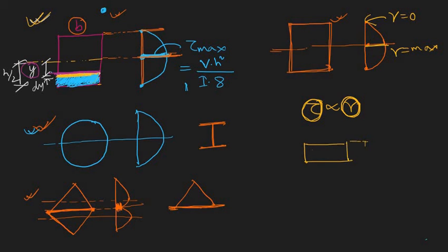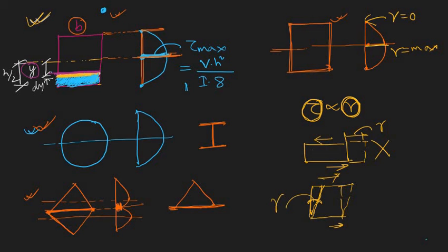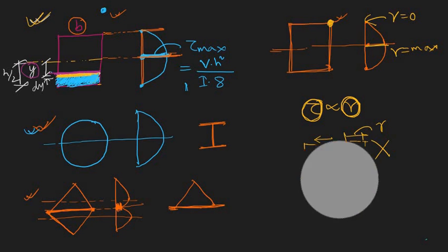Now for a shear strain, it is not a displacement like this one. It is not a displacement like this, that you are applying some shear force like this and you have some displacement. This is not gamma. This is not true. For this one, the strain is an angle. So if you have shear stress like this, it has deformed, so this is the strain actually, gamma. That means at this point gamma is 0. Let's try to visualize that.